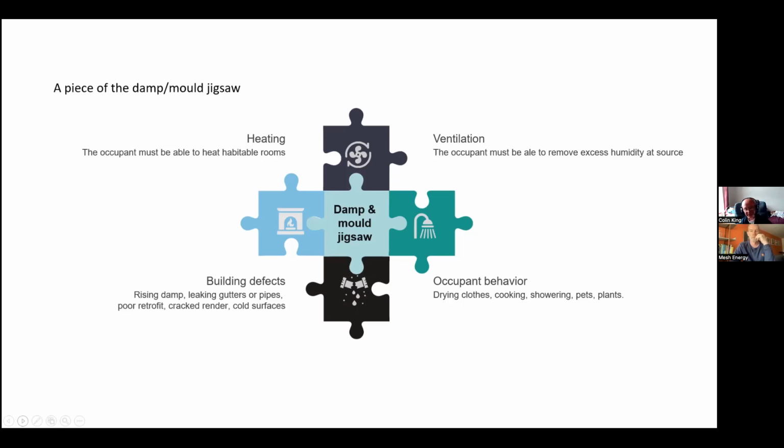The ventilation has to be right. And if you look at the new Part F, you'll find that just putting in 2 intermittent extract fans is not enough. It doesn't deliver the whole house ventilation rates required. You need to be thinking about DMEV at the very minimum as a ventilation system, and minimum 9mm undercuts and trickle vents in every window. That way you are capable of getting somewhere close to the requirement for background ventilation.